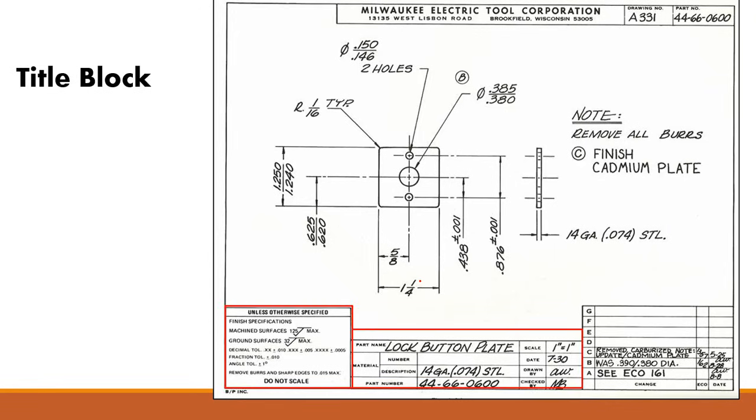First, it gives you a title block. A title block is the information that lets you know about the company as well as the drawing. When you look at a title block, you'll know not only what the part name is, you'll know any part numbers, who the engineer is, the scale that you're looking at the part at, and any crucial tolerances for that part.